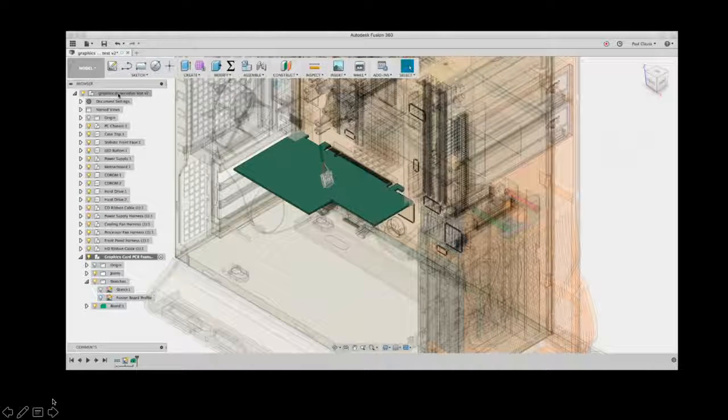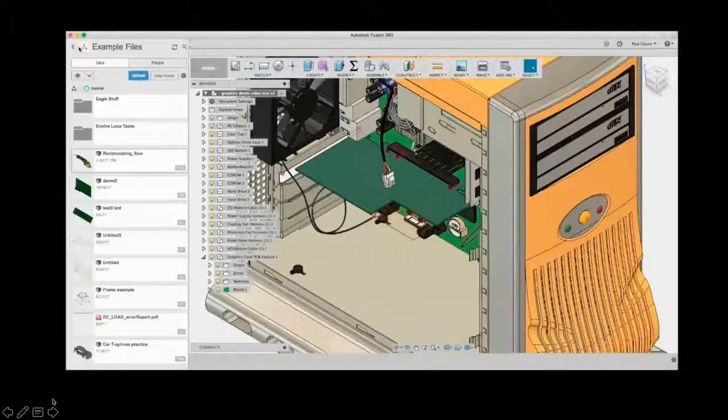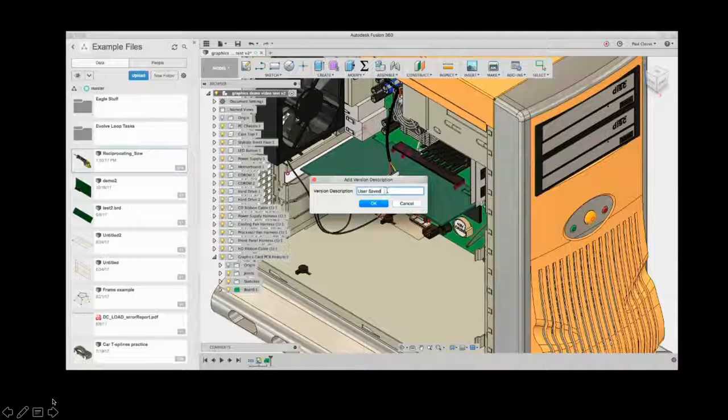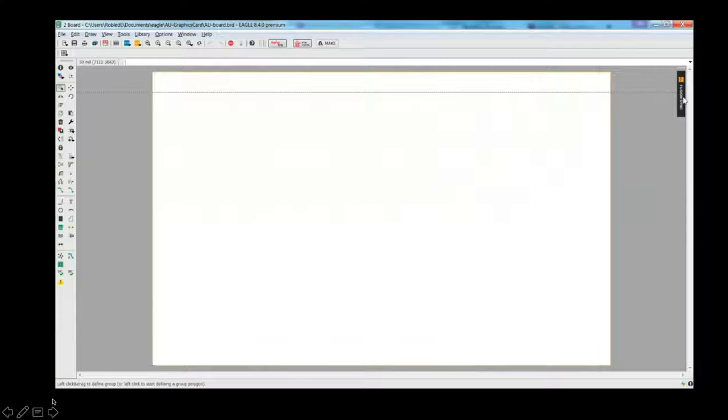So when you're defining your PCB, it actually gives you the option how thick it is. But we've used default values in this. That way it uses the most common type of prototyping house. So that doesn't need to be modified, but it can be if necessary. And one thing I didn't go into much detail there on is we can redefine our axes for the board. So I'll leave some comments that Edwin will see in the Fusion sync, ready for pull to Eagle, and then we can go into Eagle.